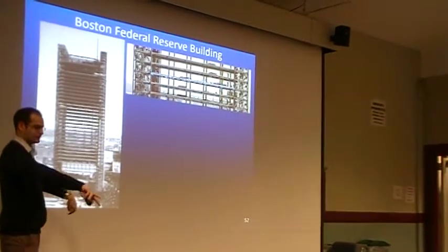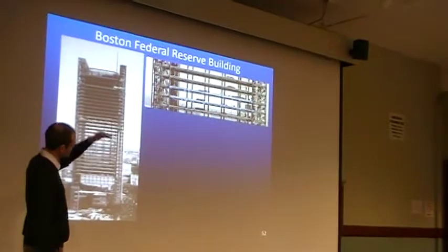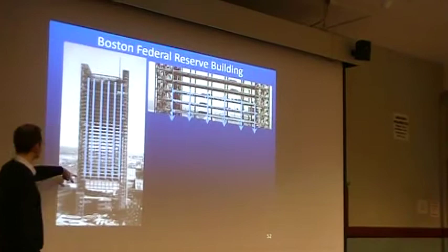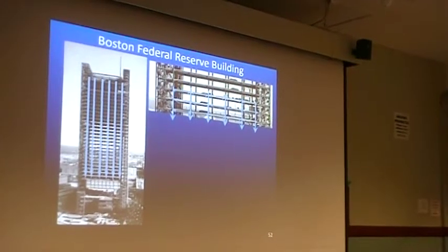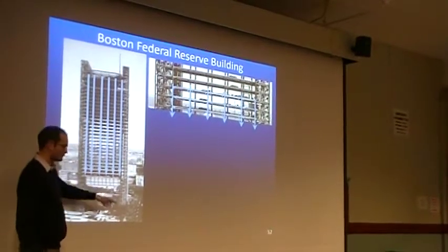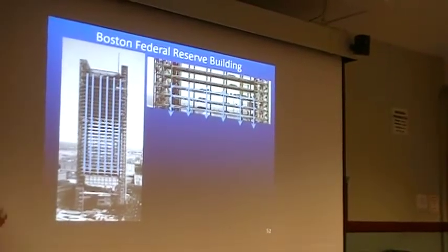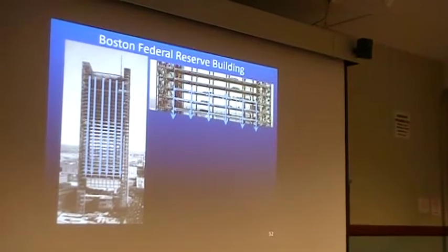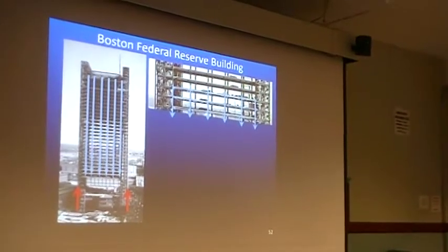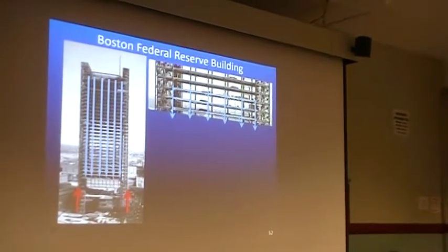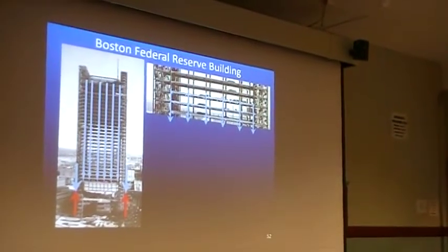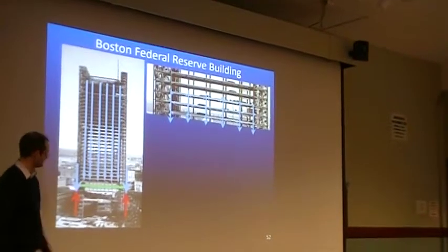It's a beam's job to get the load to the columns. Every floor has 630 tons. The columns' job is to collect them and send them on down. In a normal building, you want to get it to the ground as quick as you can. So in a normal building, these columns go all the way down to the ground and get to a foundation. But in our case, we need, desperately, to take that juicy dead load and get it over here to resist this uplift force to keep our building from falling over. So we need that force to end up over there. It's conceptually necessary to put something over here.